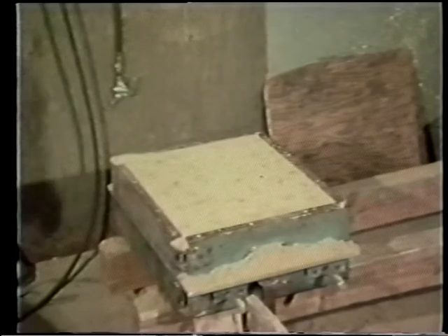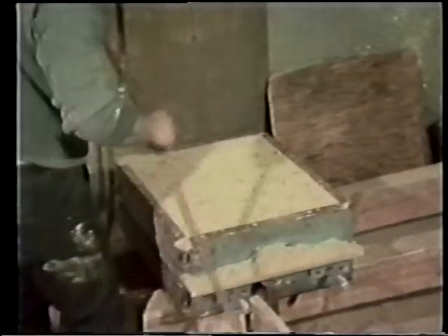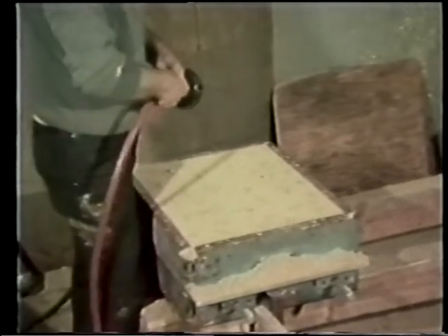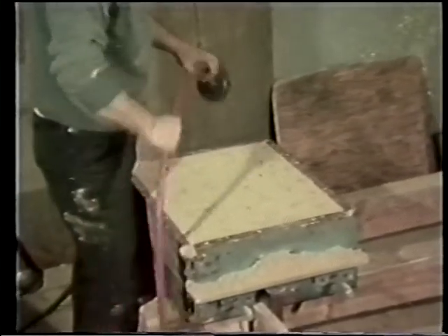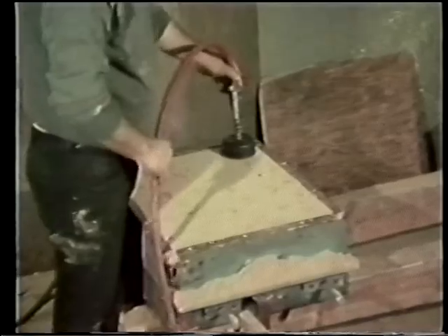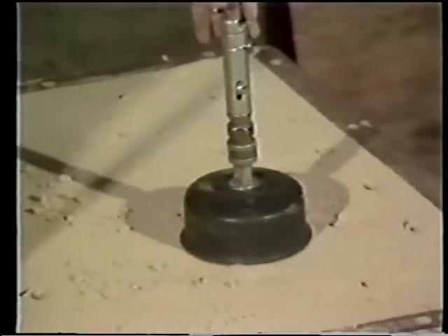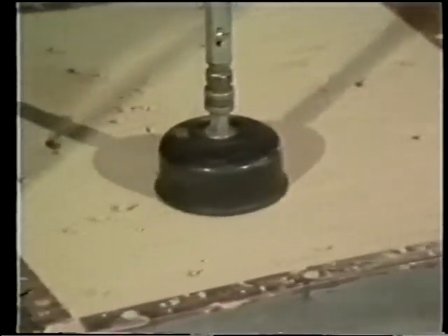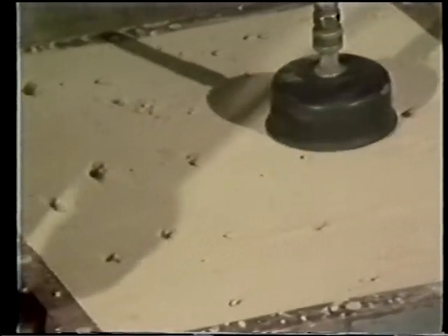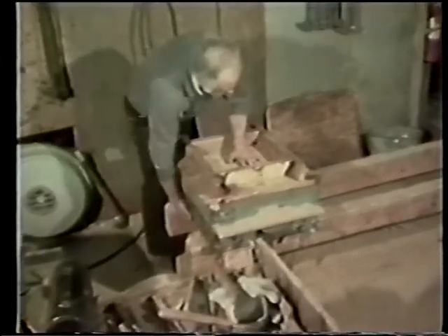In this instance, holes are poked through the mold to allow compressed gas to enter the mold material. The sand is hardened by pumping carbon dioxide into the mold through the holes. The CO2 reacts with chemicals in the sand to produce almost instant hardening of the entire mold. The mold is now turned over and the other side processed in the same way.